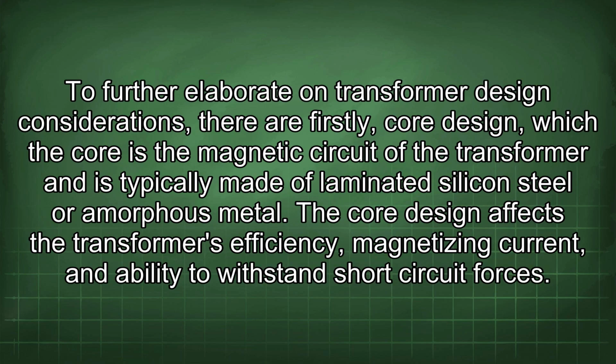To further elaborate on transformer design considerations, there are, firstly, core design. The core is the magnetic circuit of the transformer and is typically made of laminated silicon steel or amorphous metal. The core design affects the transformer's efficiency, magnetizing current, and ability to withstand short-circuit forces.